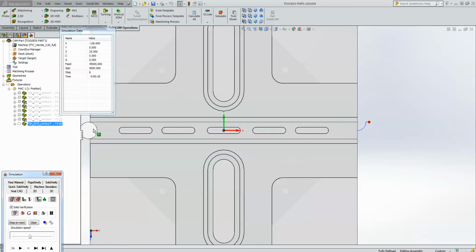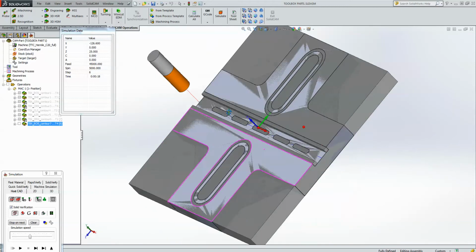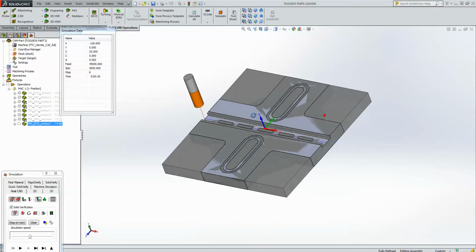You can see the tool comes up to this point over here, past 10% past that edge over there, and basically we're done doing that slot over there, as shown over here. Okay, now my next step that I like to do is I like to have a pass on this face over here as well as this face over here.